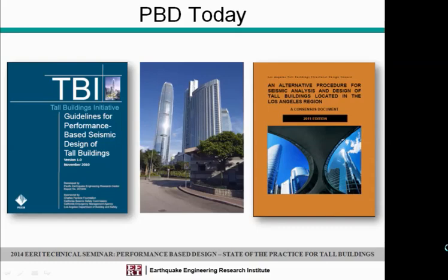However, as I and other speakers in the room will tell you today, even though what the developers want are buildings that will perform as well as, not any better than, but as well as a building designed to the building code, we in fact believe that these buildings we're designing using these procedures will perform better than buildings designed to the building code, because the analyses that we're performing are much better able to predict how the buildings are likely to respond than the modal response spectrum analysis used in the building code.